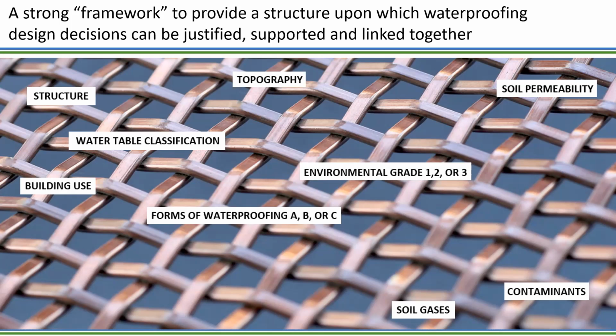Or is it type C, which is a passive system really, where we essentially line the internal faces of the structure with studded membranes which act to intercept and guide any minimal water ingress to a planned system of serviceable drainage and thence to sump pump systems and things like that. So these are in my armoury. Yeah, I can choose type A, B or C for my systems to protect a certain grade of environment, or I can combine these systems to minimise risk, as far as possible to the nth degree.